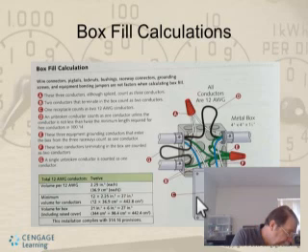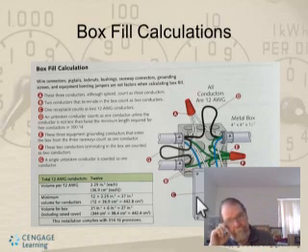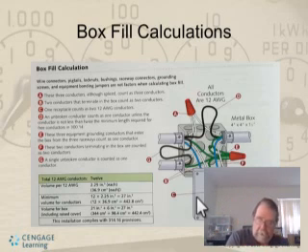And the maximum number of conductors looks like we can get up to 12 conductors at 2.25 is 27 cubic inches. And we have a 27 cubic inch box. So we're just right. We're legal with the receptacle and everything in there.